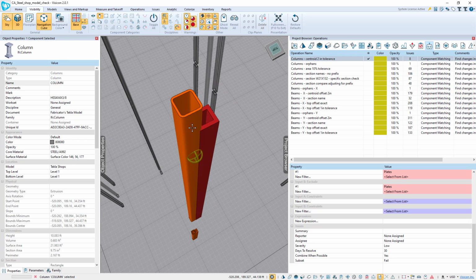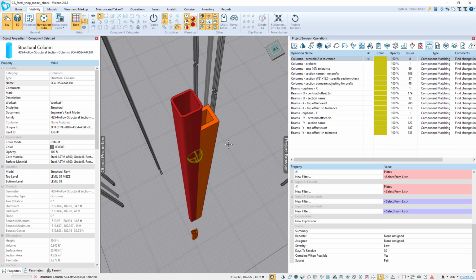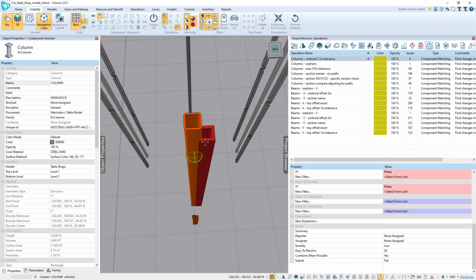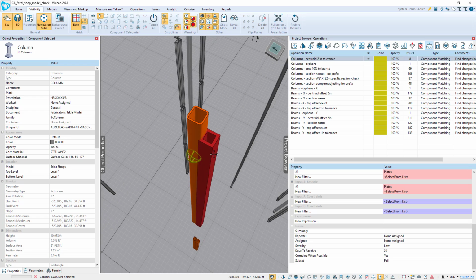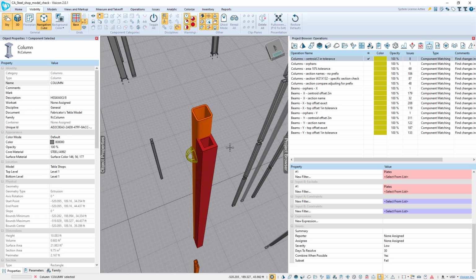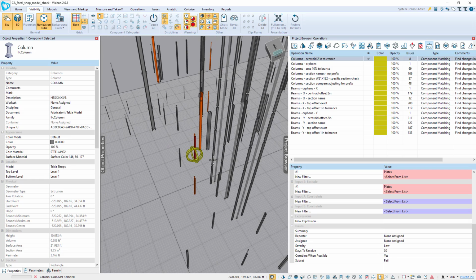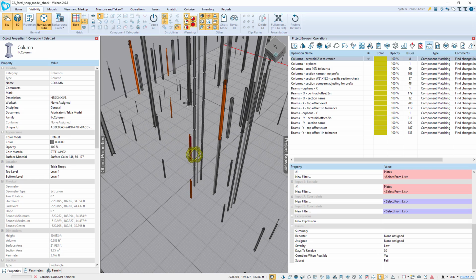Their representation might be different, but they're the same exact member designation, right? They're both HSS 4x4x3/8, so that's why it didn't trigger a fault before. It just happens that Tekla shows it differently than the other, but our center line is still too far beyond our tolerance. What I want to say is, you can come in and set these up as you wish.